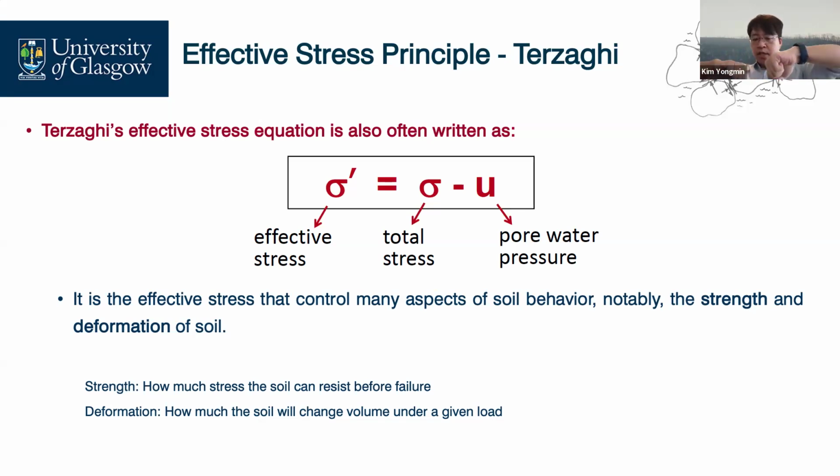That's why they contact each other, and then when I press this way there should be some resistance. This is shear resistance, shear strength, but water totally cannot. So when you are dealing with soil strength, we mostly talk about the effective stress concept.